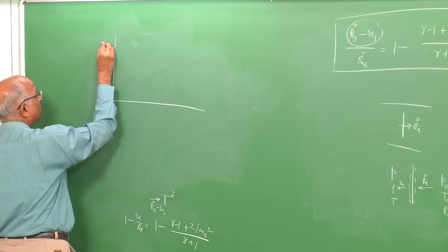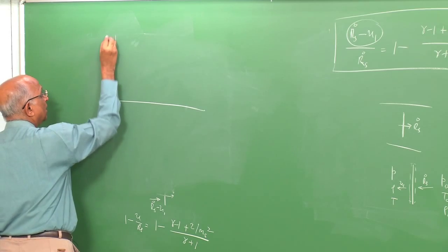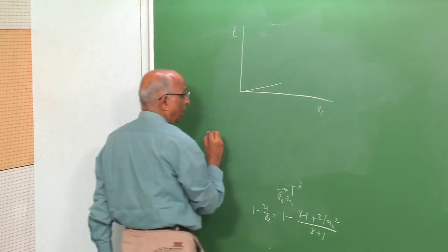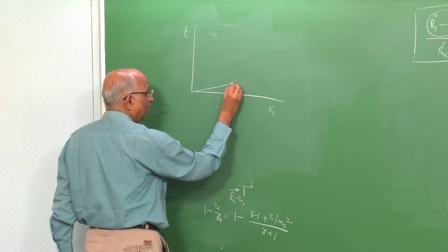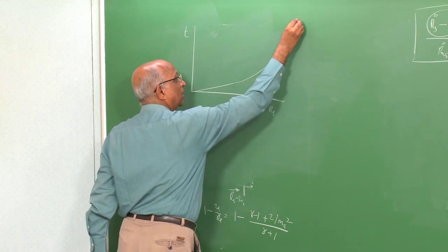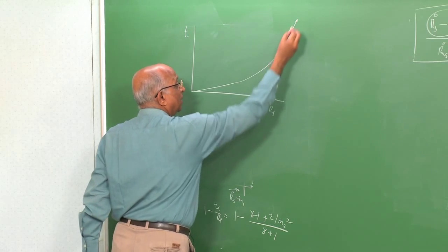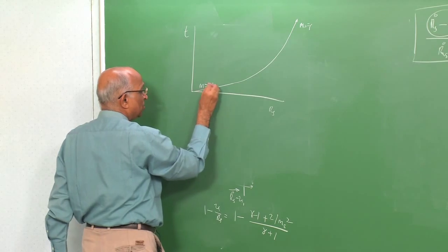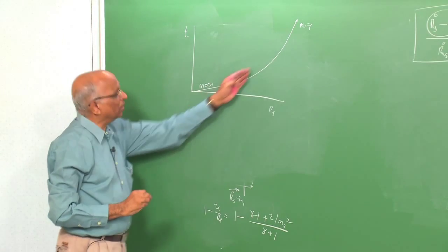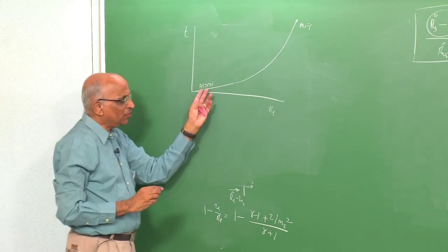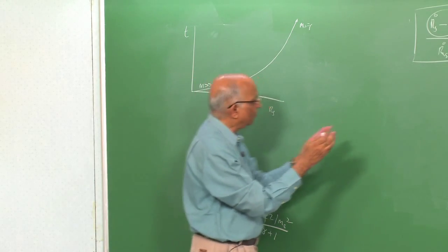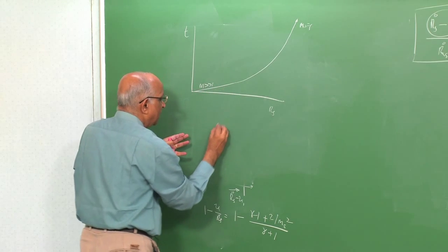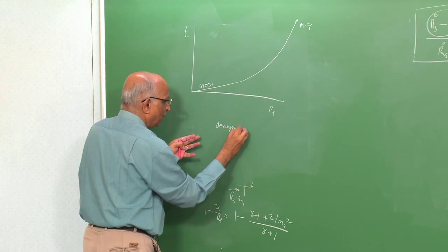We are interested in something like, let us say, in the streak diagram T versus Rs, we start with a strong shock wave travelling at high velocity and it keeps decreasing, ultimately it becomes an acoustic wave wherein the Mach number is equal to 1. It starts travelling with a Mach number which is very much greater. Now, it is a variable Mach number, and how do I use the results I have derived so far for the case of a decaying shock wave, which is a blast wave?